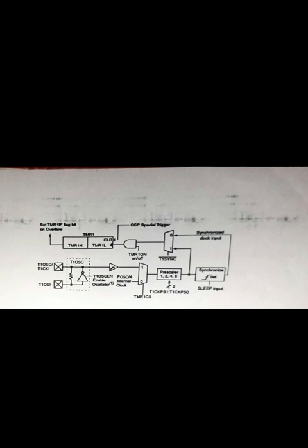a crystal oscillator. When it is the crystal oscillator, then the T1 oscillator logic, if enabled, will get the clock pulse from the crystal oscillator. If it is disabled, it will get the clock pulse directly from the T1 clock input pin. The prescaler bits are used to divide the incoming clock by any one of the factors 1, 2, 4, 8.